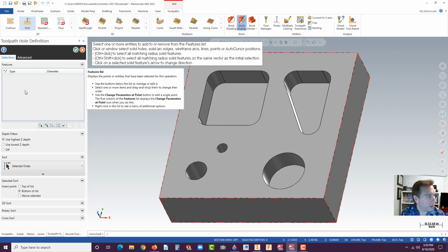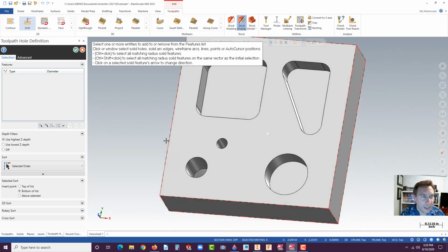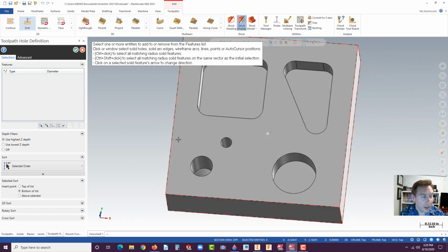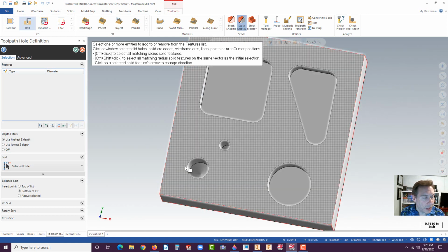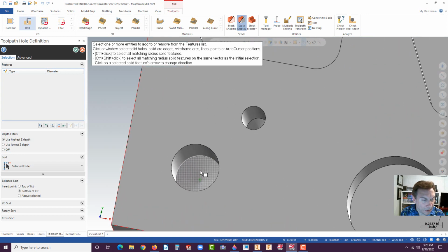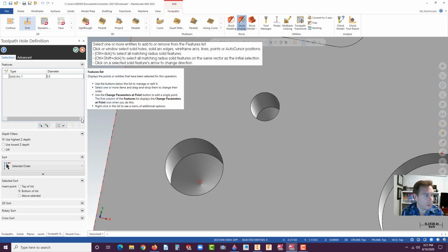All right, so now here's where we get to select the entity. So we're going with the drill process. And to rotate this, unlike Inventor, where you remember you were shifting the wheel, this is just the wheel. Push it down, hold it, move your mouse left, right, up and down. You could rotate. Now go ahead and select this lower edge. Be really careful when you look in this pocket. Make sure this edge glows, because that's what you're going to want to select. You don't want the upper edge, or else it's just going to stop right at the top there. You want it to go all the way deep. So click on that. You'll get a little red cross, and that's good.